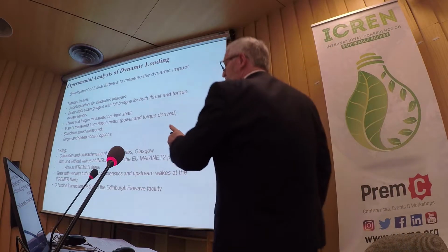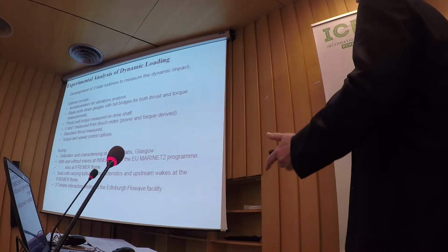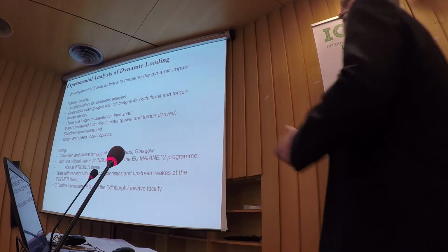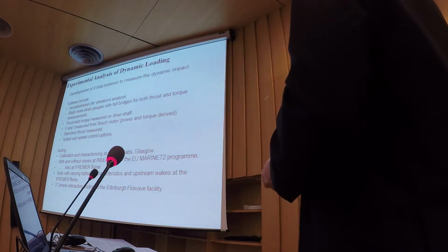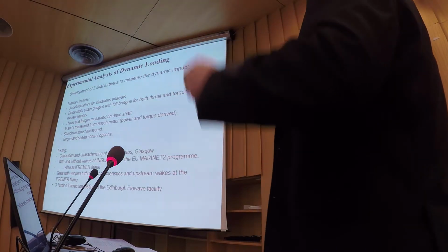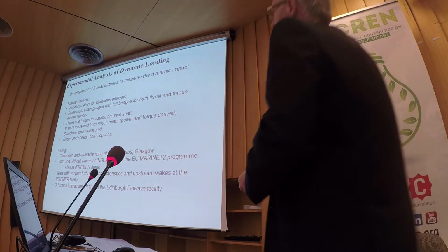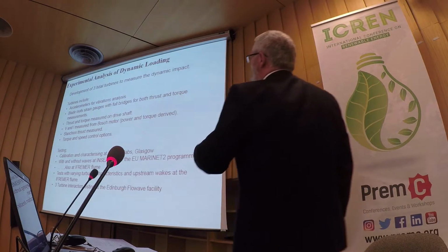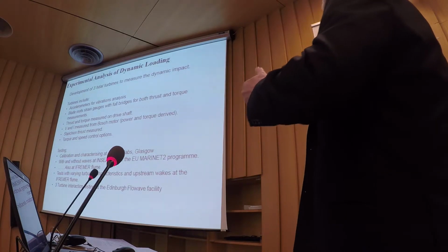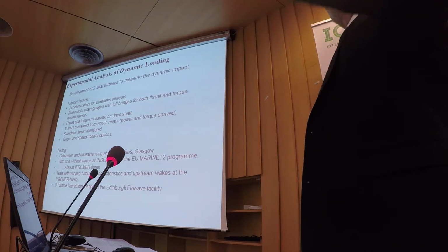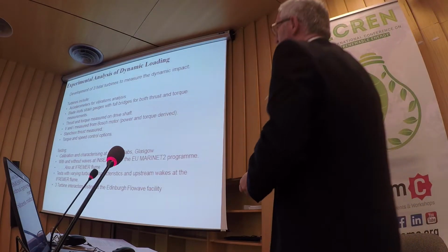So, in order to show some of these things, we've got 3 tidal turbine models, each of which is equipped with instrumentation that can actually measure the dynamic quantities that are coming out. Accelerometers on the stanchion, blade root strain gauges for thrust and torque, thrust and torque measured on the drive shaft. Now they should equal the sum of the blades.